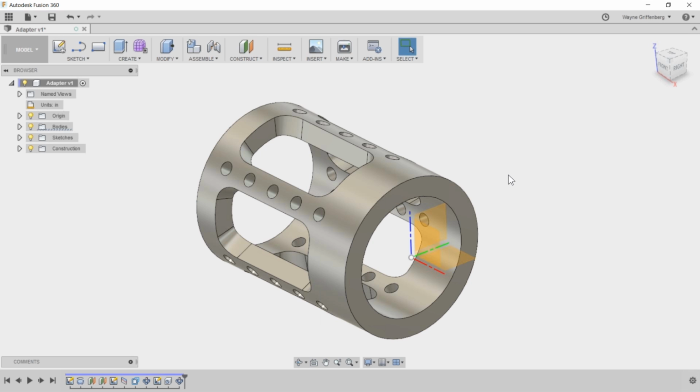Mastercam G-code, no, we're not able to bring in any G-code from an outside source. Even our own G-code, there's no. Oh, let me answer this again. Maybe I'm misunderstanding the question as in modeling, because my mind's thinking of modeling. We can, in our editor, open any G-code, and you can edit any G-code through our editor. That's not a problem. I misunderstood, thinking, could we recreate a model, or could we do a toolpath from G-code? That we can't do. But yes, we can open up G-code and edit it and change G-code in our editor. Okay, so that should answer that question.